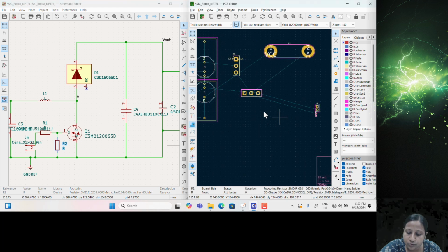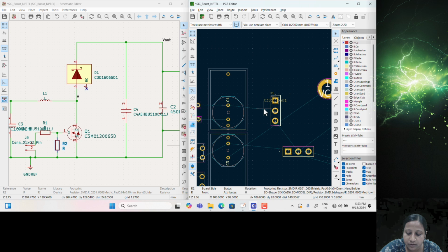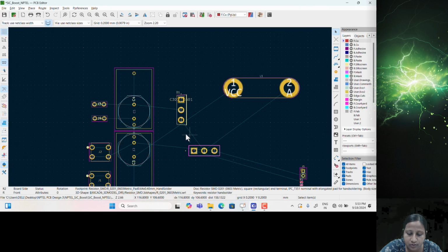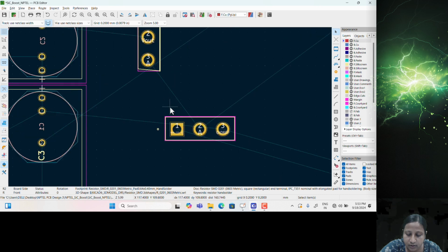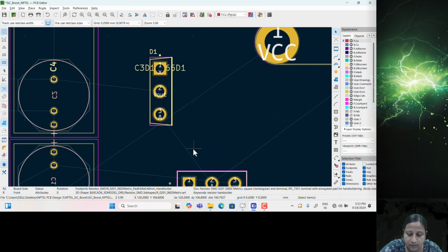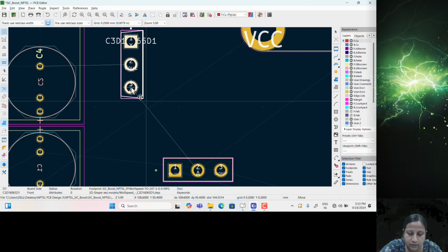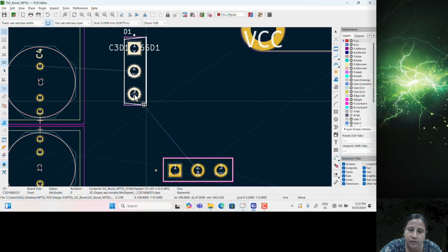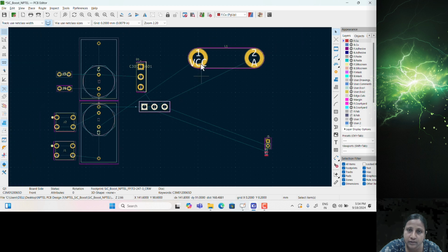You can also choose SMDs for the main devices or the capacitors connected in the power board itself, but at this moment we haven't selected that. It will be easier to connect through-hole components rather than SMD components. For resistors it will not make much difference, because the connection may not be that difficult.